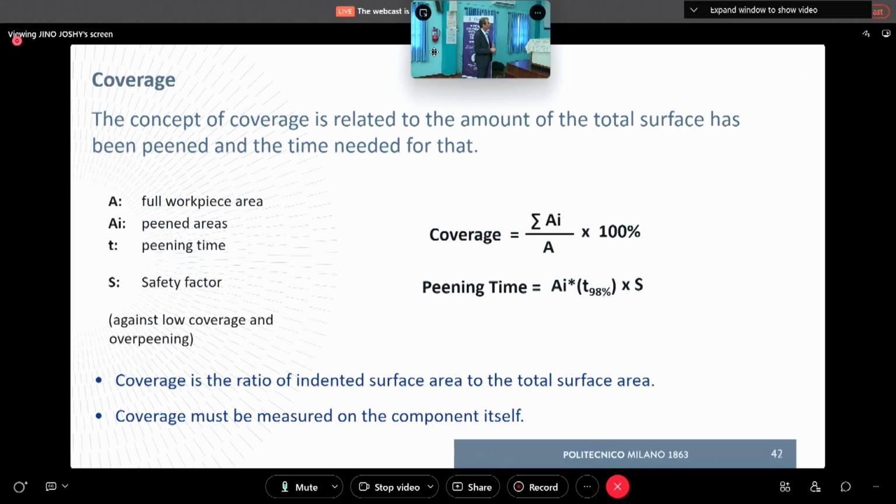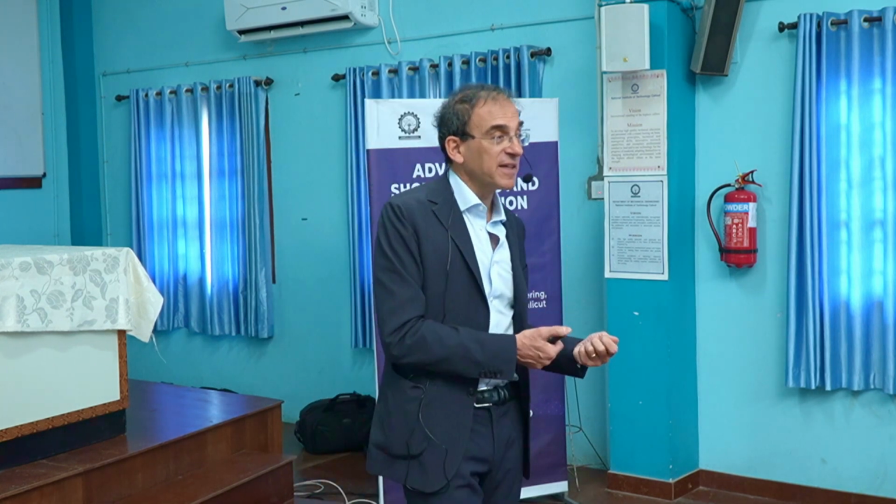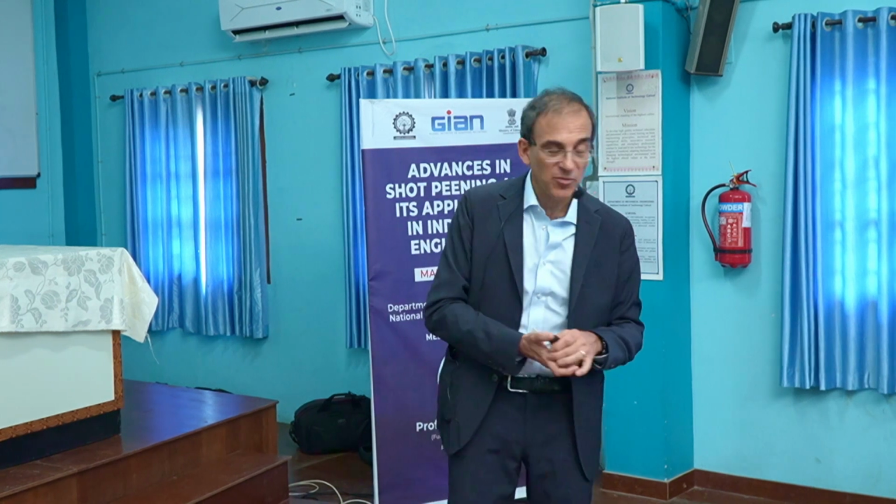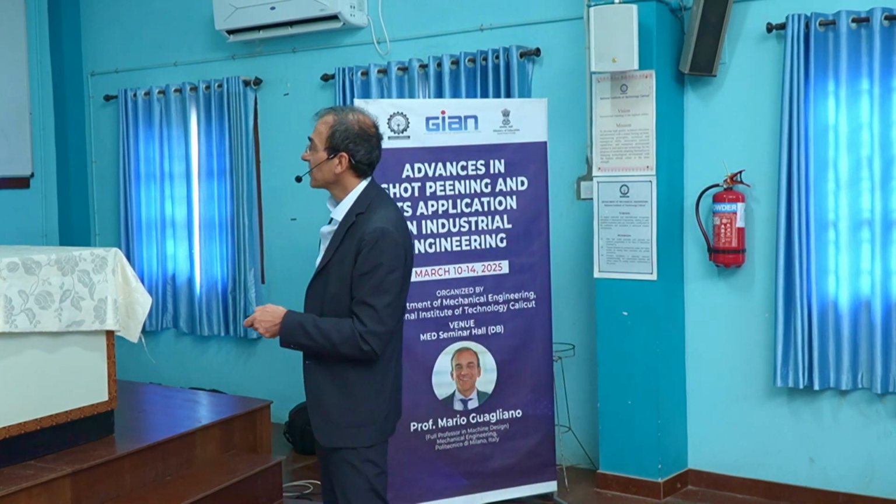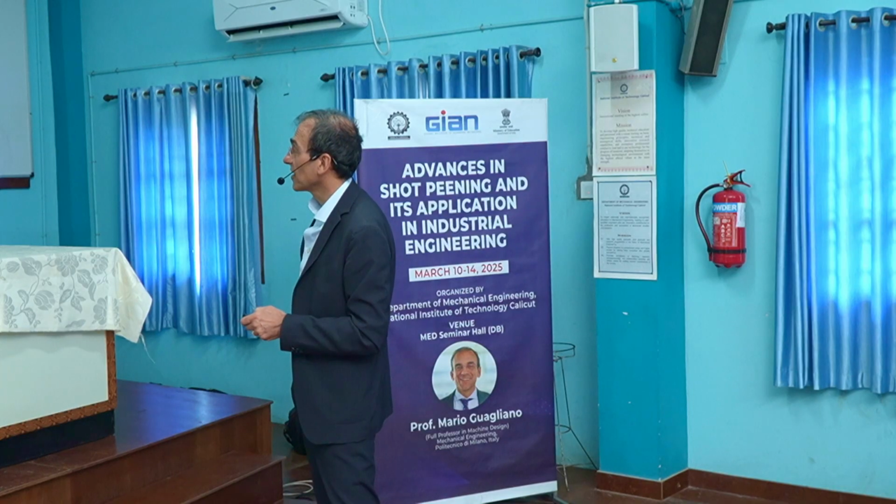The peening time has a safety factor S that considers the possibility of overpeening and also of underpeening, that is to say that the coverage is too low. As I said, 90% is considered as acceptable.